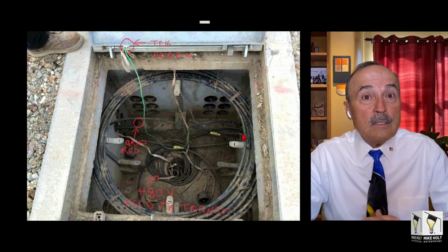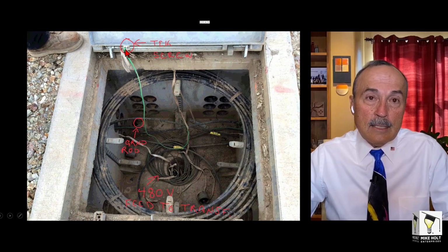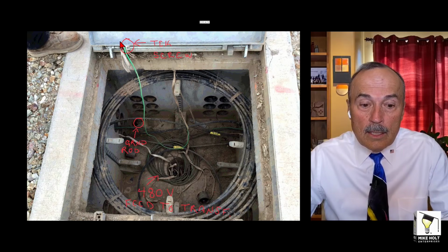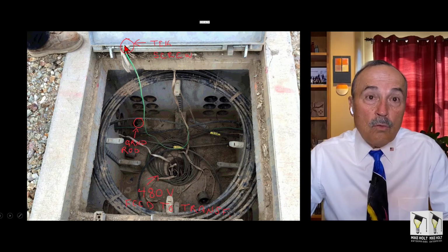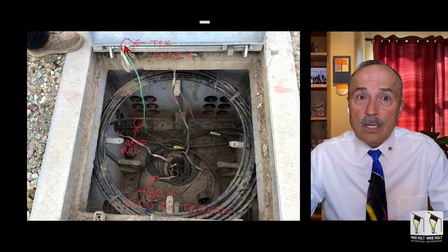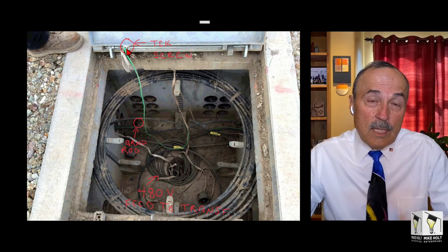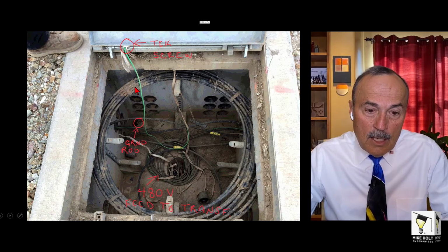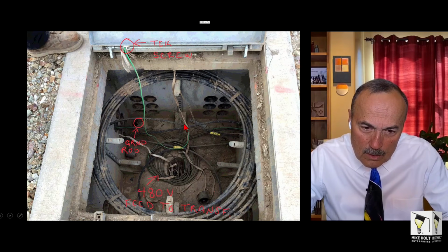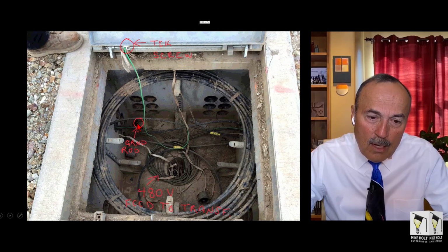Let's get back over to this manhole. Here's a metal cover, and they use a Tek screw to connect to it. That's a violation of 250.8(A)(1). Then they take this ground wire, but it's not a grounding electrode conductor, because a grounding electrode conductor is only where it is required. 250.66 talks about it. Here's your ground wire, and if you follow it, somehow it goes around here, around there, and goes to this ground rod.